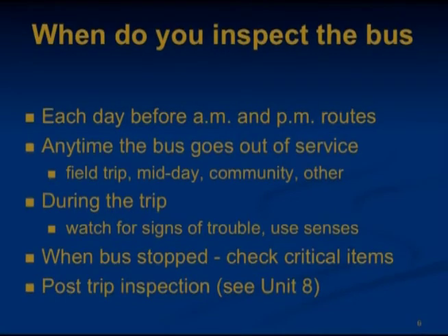Homeland Security requires us to check the bus once an hour for tampering or vandalism. To prevent accidental rolling, pump your service brakes down to 20 to 40 psi during the layover. While driving the bus, you should watch gauges for safety and signs of trouble. Use your senses to check for problems.